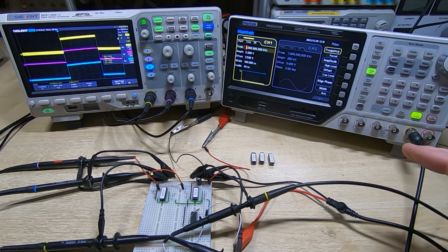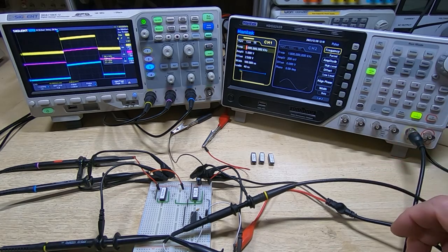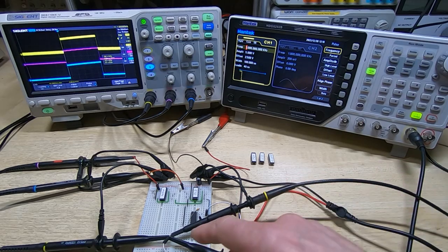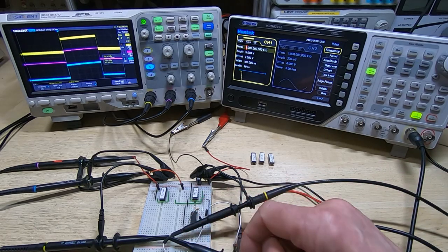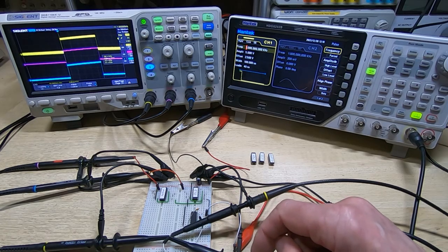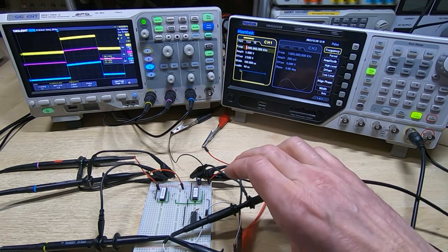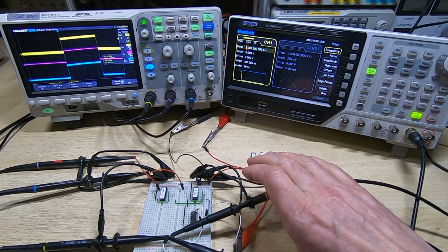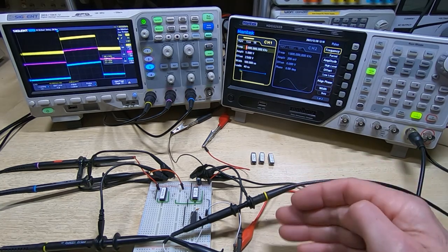I'll move the camera, we'll look at the LeCroy, and that's a 5 gigasample per second scope, 500 megahertz bandwidth, and we'll look at one of the expensive probes and one of the lower cost probes. They're both connected to the clock output from the buffer chip, so they should both be showing the same thing. And again, yes, we're using a breadboard, but this will have absolutely no bearing on what we're looking at in terms of comparing the two probes.